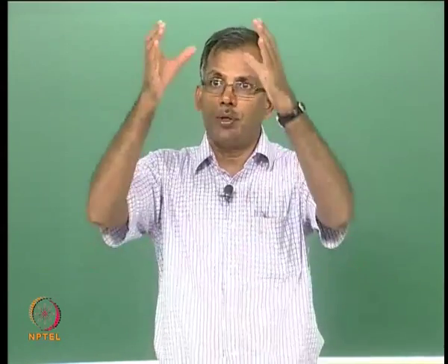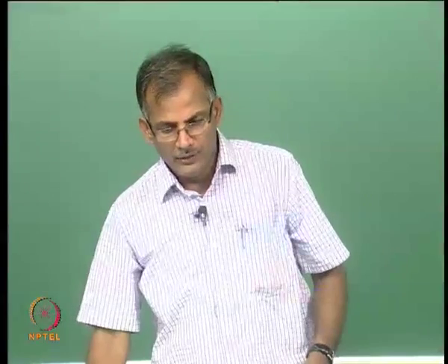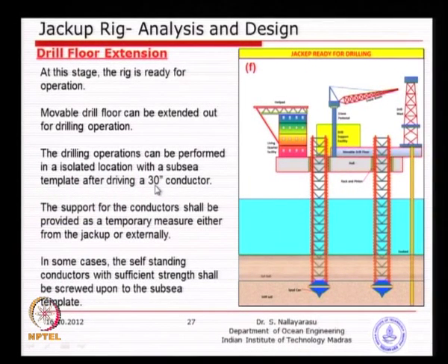So, you need to have a protecting casing. That is where we discussed these so-called conductors. Conductors are only protective casings through which you will start doing your drilling. So, first you will install such conductors, but unfortunately 30 inch is less than a meter, and it cannot span a water depth of 50 meter, 60 meter, is it not?